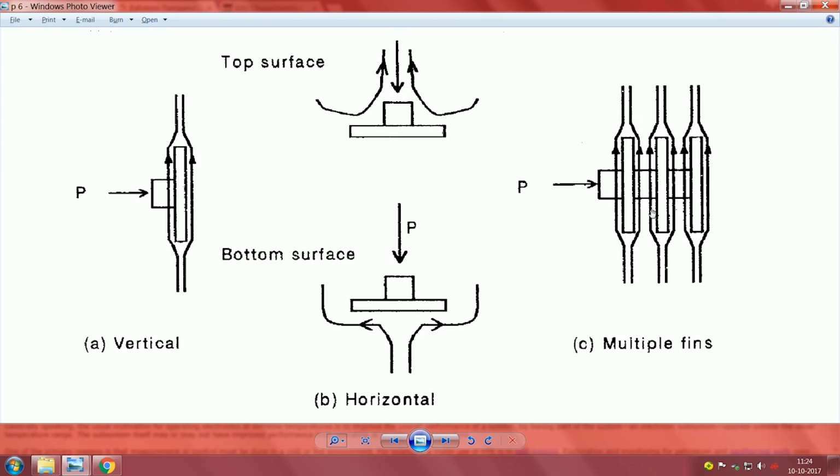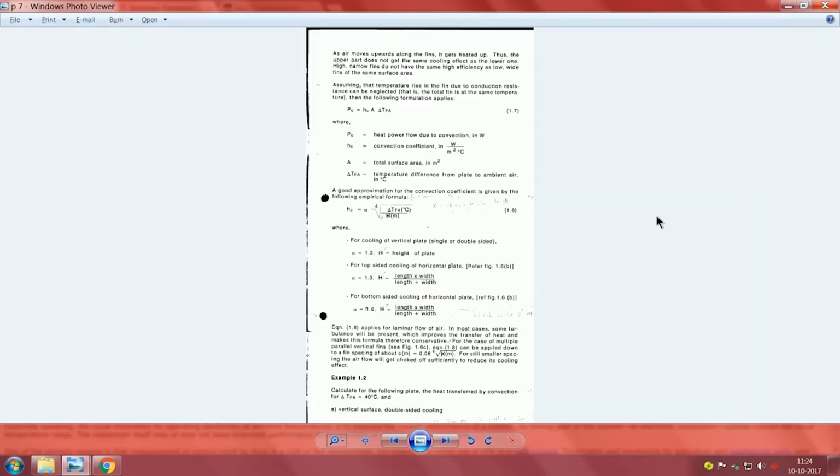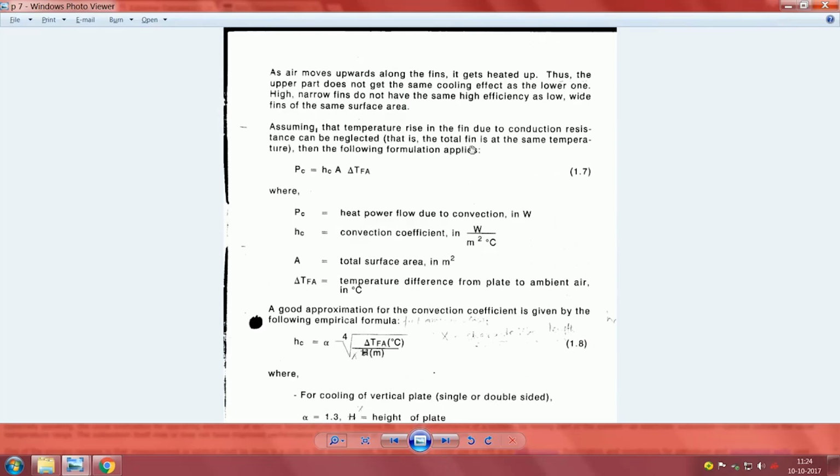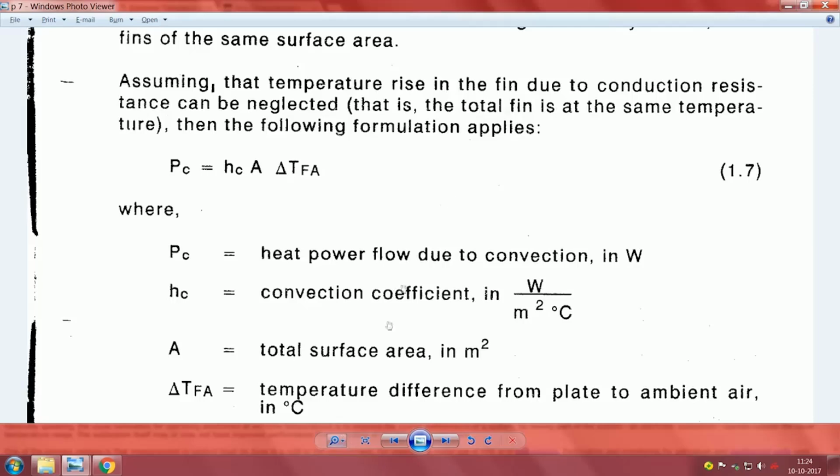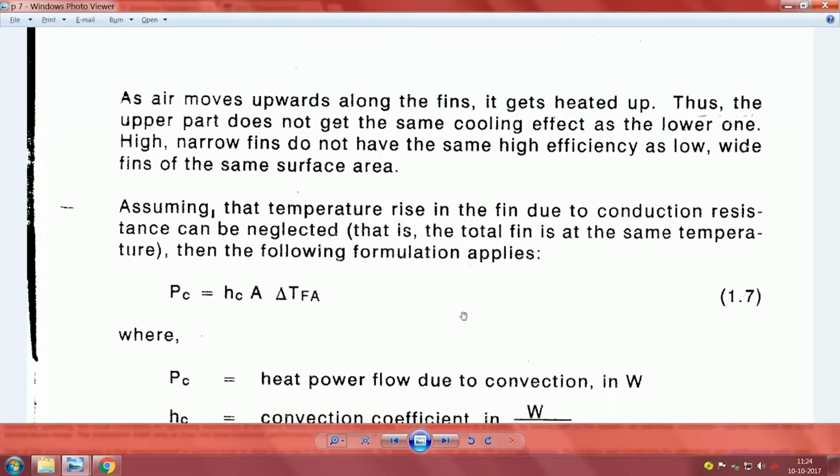Where these are useful is, imagine you have an enclosure which is carrying all the heat. So, you have a top surface in which some heat is lost, and you have the bottom surface. If it is elevated, usually on rubber feet, cooling can take place, and then the extreme left and right surfaces, where these things can be improved. Now comes the other question: is there a way for us to increase the surface area? So, we come to this beautiful idea: why do we not just put more and more fins?